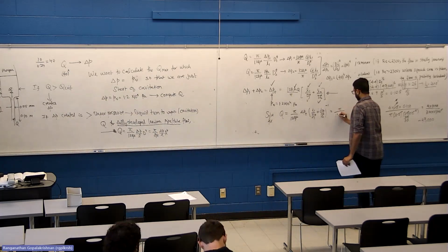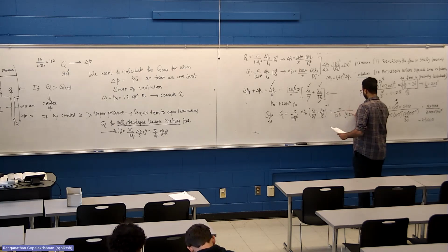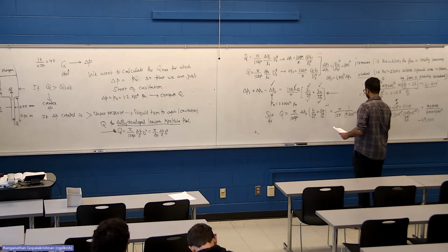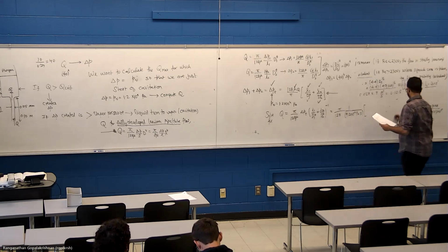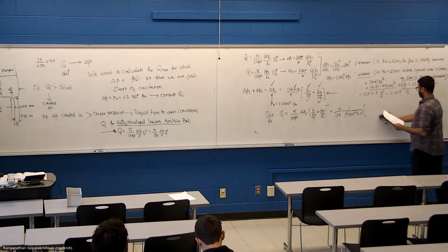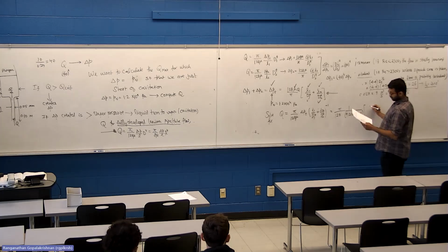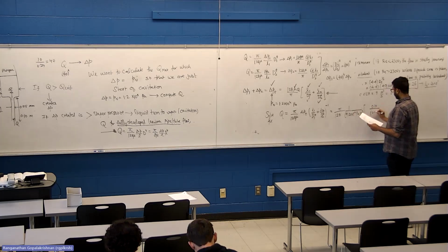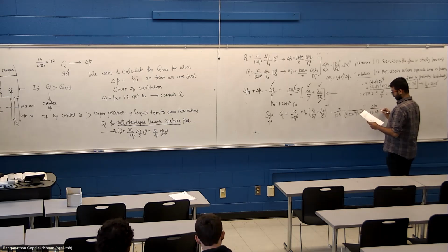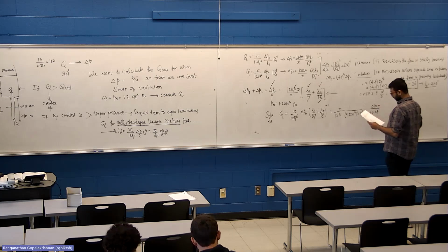So this is pi over 128, 9.2 times 10 to the power minus 4 Pascal second, times L1, which is 0.10 divided by D1, 0.25 millimeters.